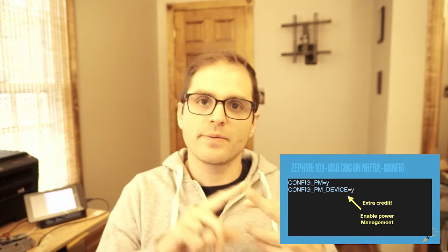Any pins that are allocated to some other function, so the NFC pins are by default set up for NFC. If you're ever running with an nRF52 device and you're trying to use those pins for something else, there's actually a configuration variable to turn that functionality off to allow you to use it as a GPIO. Same thing with the reset pin, port 0, pin 18. By default, it is the reset pin. So that's just something you need to turn off to allow you to use it as a GPIO.